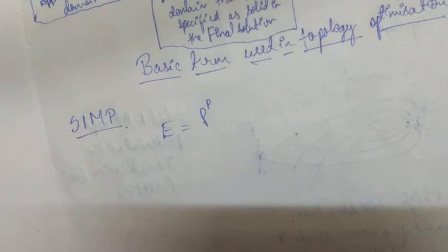There are two basic approaches to topological optimization with the SIMP technique: minimum compliance design and minimum weight design. The latter minimizes the mass of a structure within constraints on a specific performance measure. The specific performance measure is usually defined as stress, displacement, buckling load factor, or any combination thereof. And we have seen the application earlier.